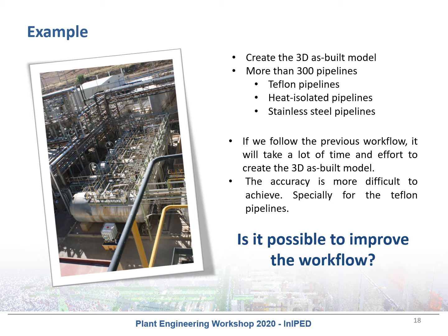A solution can be trying to find in the market a software that automates, from the point cloud, the object recognition and their extraction to the 3D as-built model. Another possible solution is that we follow the previous workflow to create the 3D as-built model. When we finish it, we verify the quality and the accuracy of the model by comparing the 3D model with the point cloud.